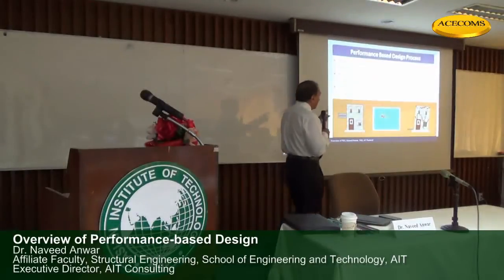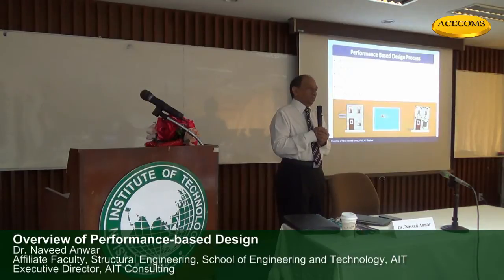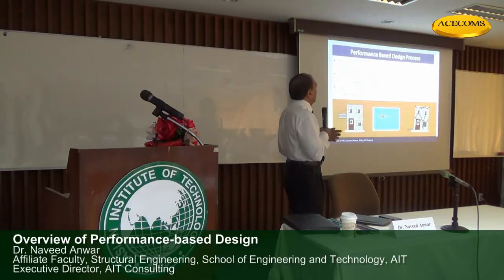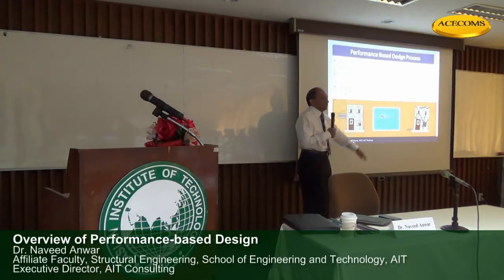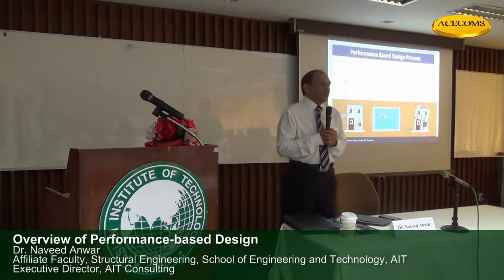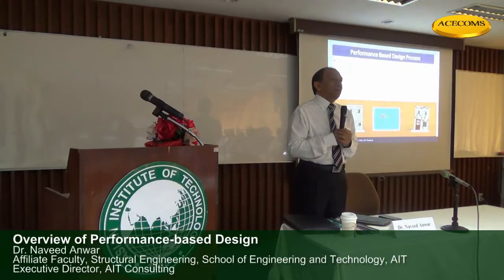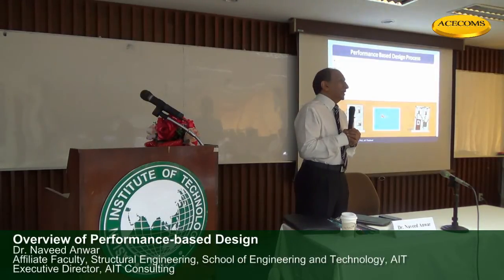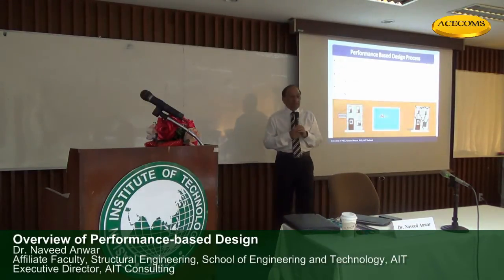However, if we are talking about collapse prevention and MCE, we have no choice. We have to use nonlinear static analysis, pushover, and most likely nonlinear dynamic time history analysis if necessary, right? That means nonlinearity is essential if we want to do performance-based design for anything more than frequent earthquakes or anything more than simple structures. So that means we need to be familiar with these tools and the techniques behind them.